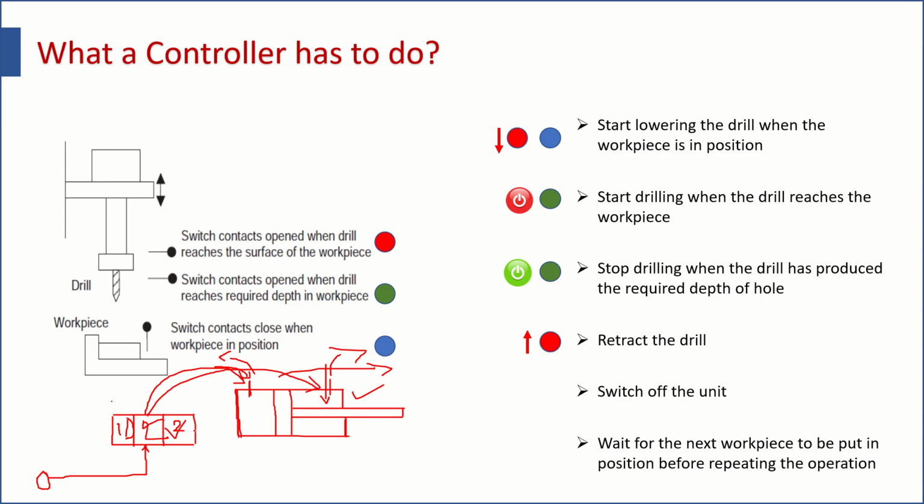Okay, so under such circumstances, you can understand very well that in order to make the cylinder go forward and move backward, you need to change the condition of this DCV like this. You need to change it from condition 1 to condition 2 in order to have continuous motion of this cylinder. And under such circumstances, when changing the condition of the DCV, to move this DCV from here to there, and from there to here, for this work you need to use a solenoid valve. You can also move it with a handle, or with a small plunger, and you can use a solenoid valve.